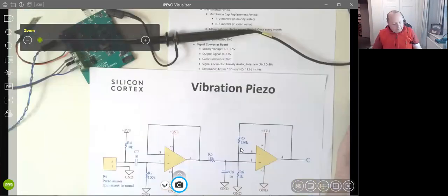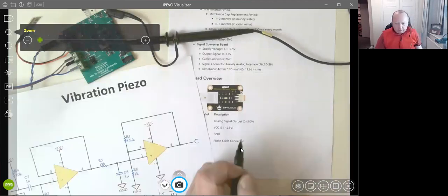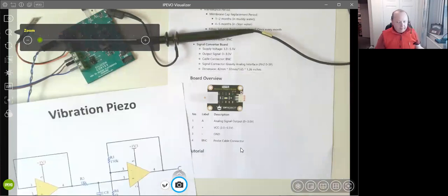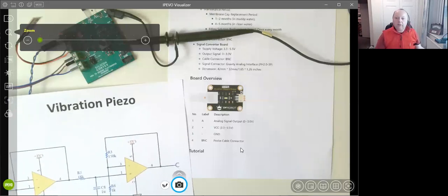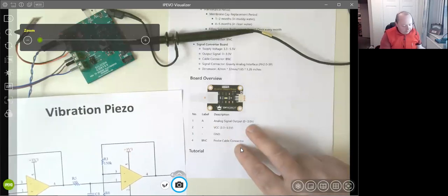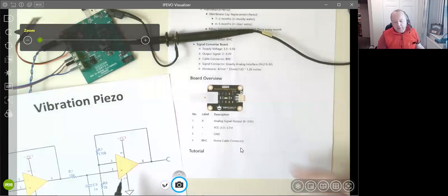Right, so different sensors are obviously going to have different output voltage ranges. If we're talking industrial sensors, they might be 0 to 5 volts. Other sensors I've worked with will just have 0 to 1 volt. This particular one here is 0 to 3 volts. If you're going into an ARM device, most ARM devices are 0 to 3.3 volts with, say, 10 bits resolution.